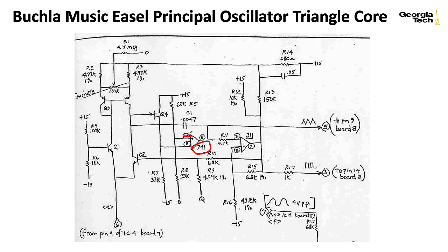It does not have a very high input impedance. And that is a problem for something like an integrator, since you wouldn't want charge on your integrator cap to leak into this input when you don't want it. So what Q4 is doing is it's basically acting as a voltage buffer. This minus 15 supply and the 33K and this plus 15, this is all rigged up for this to act as a voltage buffer. So the voltage here is being nicely buffered by this high impedance presented at the gate before it hits the negative input here of the 741.